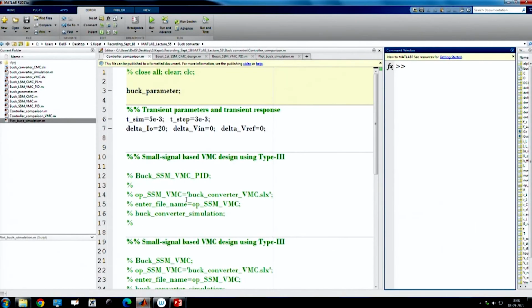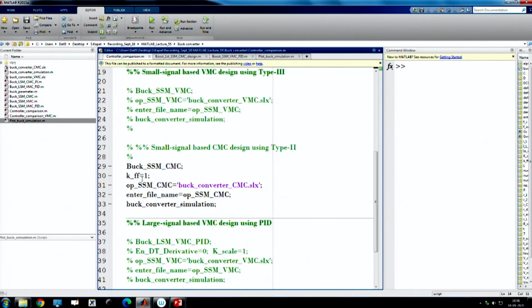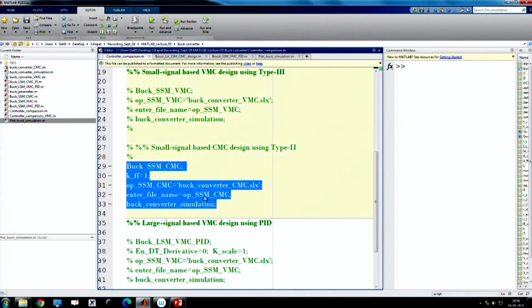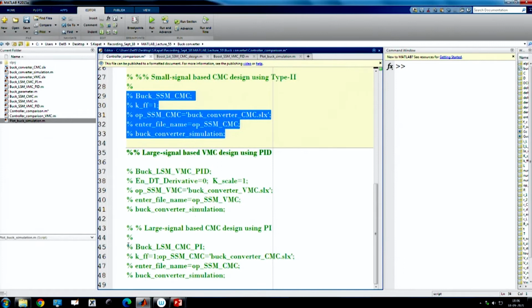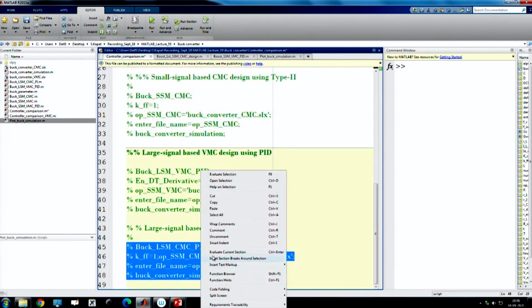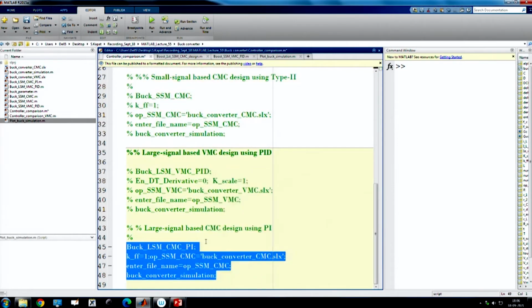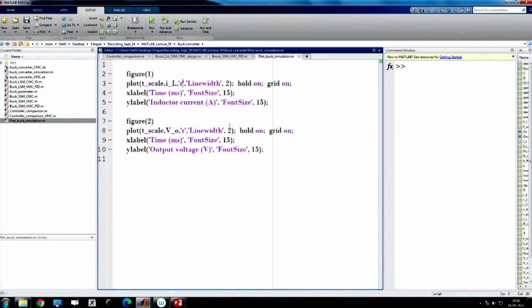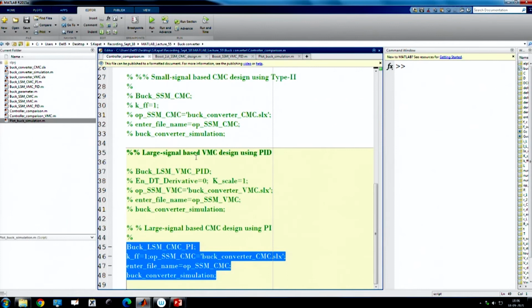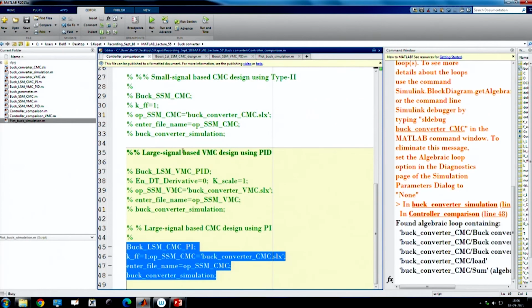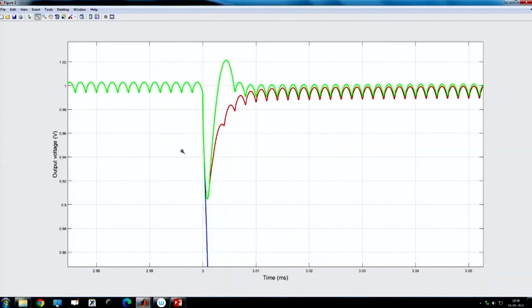Now we are going to large signal tuning, okay, for current mode, where we need to incorporate load current feed forward, and we discussed that we can estimate the load current, or you can use physical sensing, right. So, estimating load current is a good solution in digital control. So, let us do that and we will run it now using green color and see what happened.